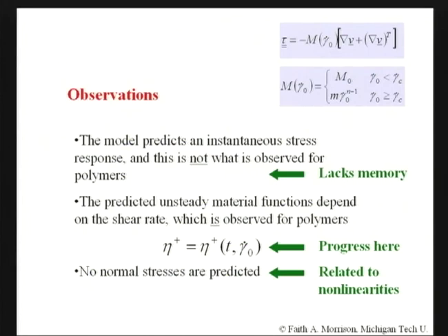So overall, attempting to fix up the model by just adjusting the viscosity and just knowing what the viscosity does as a function of shear rate, we can fix it up sufficiently to predict shear viscosity. But we can't predict the memory effects that are due to this startup and cessation business, and we can't predict the nonlinearities that are due to the normal stresses. So that's what we're still trying to get a handle on, is memory effects and nonlinearity effects.